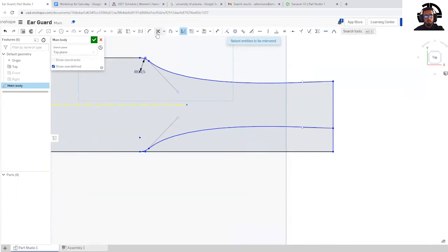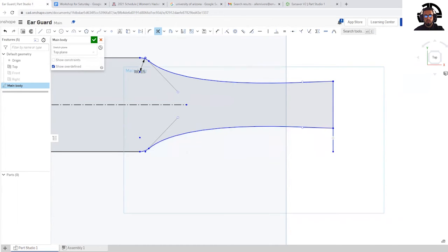So now what I would like to do is use that trim tool to get rid of these corners, since I no longer have use for them like we did beforehand. And we know that these two points are 2 inches long and also a quarter of an inch away from where we began. So I'm going to trim that piece. I'm going to trim this piece.